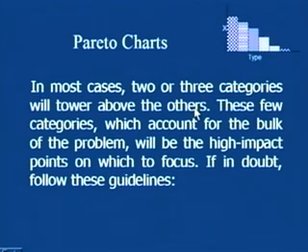So, instead of struggling to find the reasons for the trivial categories, whenever you deal with the improvement of the process or removal of the causes of defects, you should always prepare the Pareto chart and see which are the most vital problems.